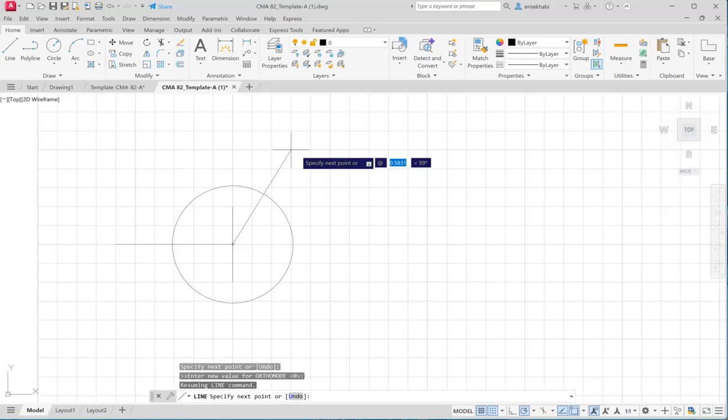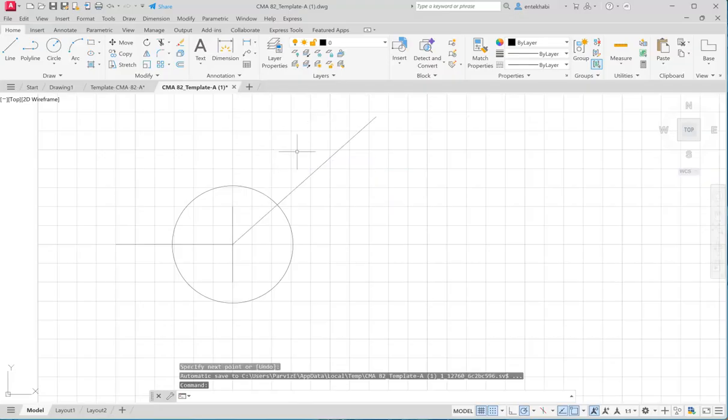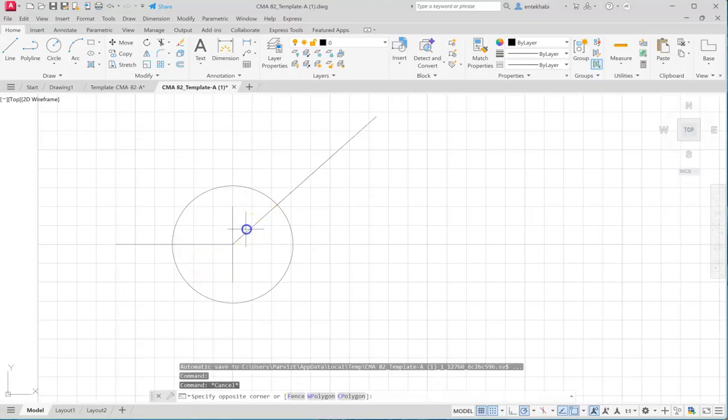It's about maybe 1. Angle sign or tab key. And then I'm going from the X direction to half of the 85, which would be 42.5. I type 1 distance with the angle of 42.5. That gives me a pretty long line, but I used that on purpose to show. Basically, that line doesn't start exactly from the center, so I need to move it.